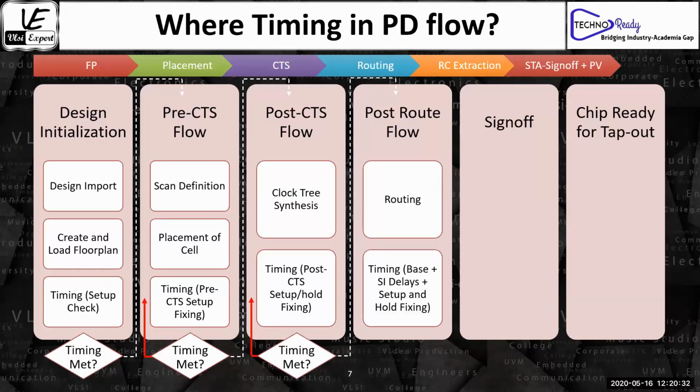And sometimes it is a part of an optimization. So if you are doing things through the tool, the tool says it is optimizing my CTS, optimizing my placement as per the timing. So they are saying a timing aware optimization. That means you provide them certain timing numbers, and on the basis of that, they try to optimize the placement, so that there are fewer violations after the placement. So that's where the optimization word comes in.